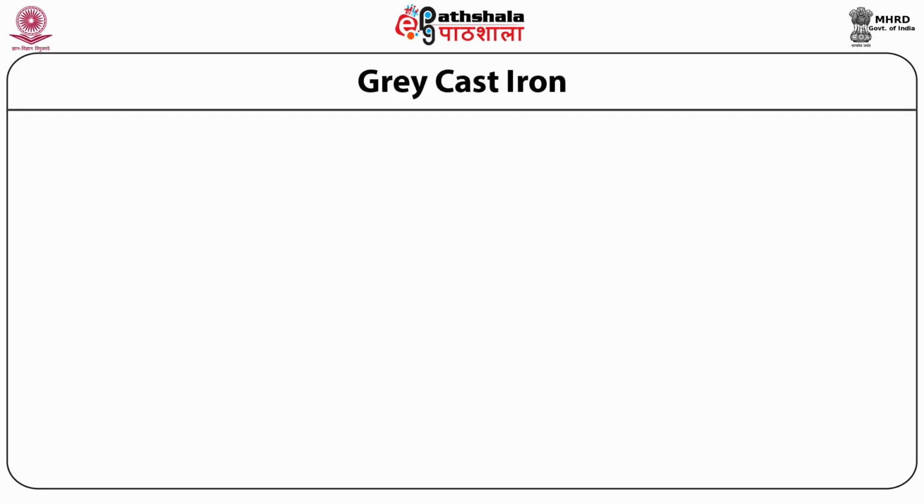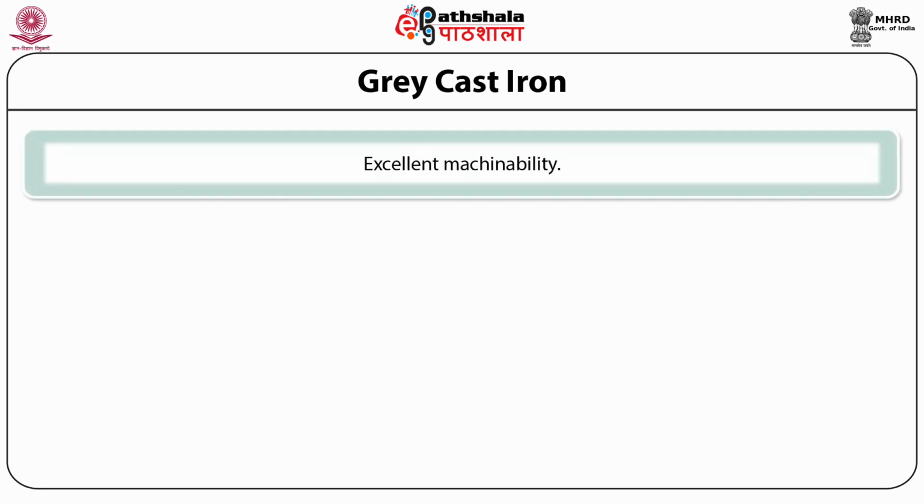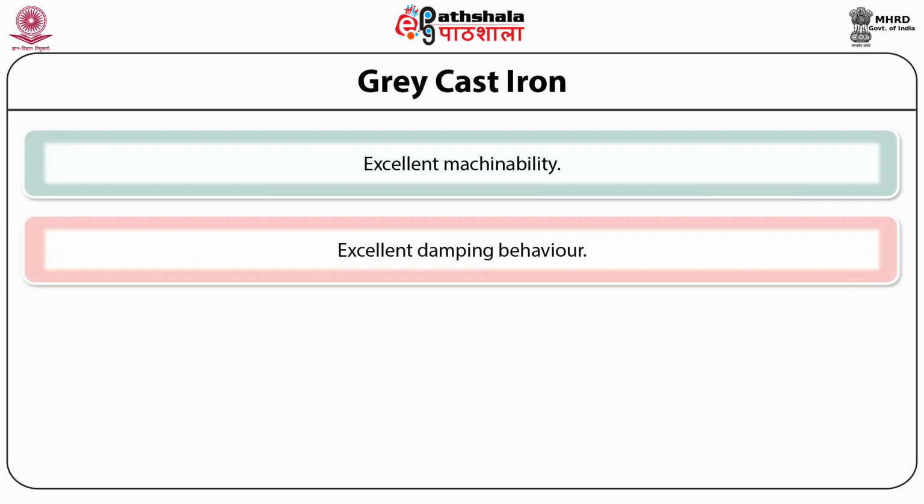Number 3, it has excellent machinability due to the presence of graphite, which acts as a lubricant as well as being beneficial for chip formation. Number 4, it has excellent damping behavior, again due to the presence of graphite.